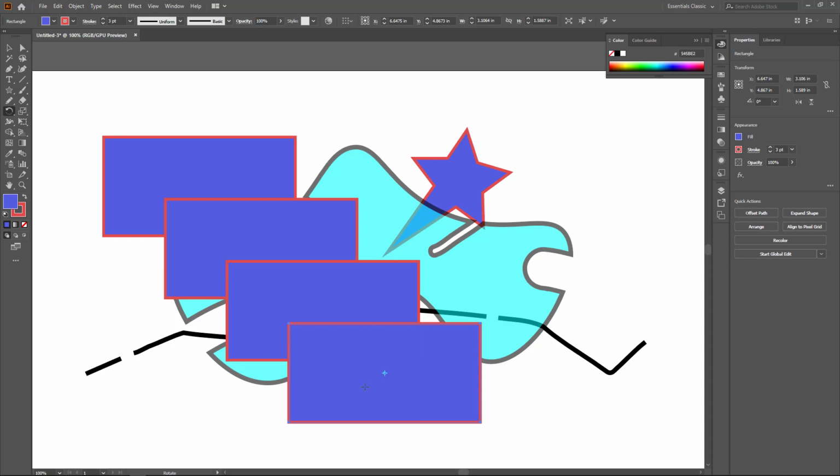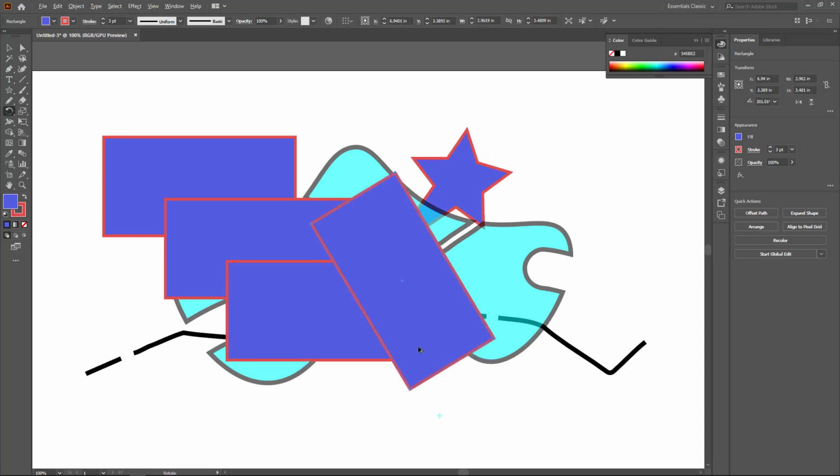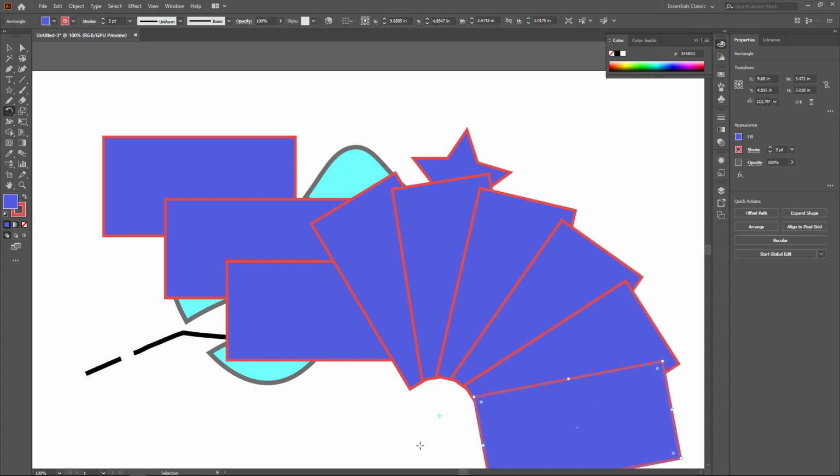Anyway, when you use the rotate tool, you can modify the center point by just clicking and dragging on it, and then just grab the object and rotate it around that center point. Finally, if you want to make a copy of this little object that we've made, you can hold down the Alt button after you've moved that central rotation point, and you'll see it can make a nice copy. And then you can do your little Control D and kind of fan out the object that way.